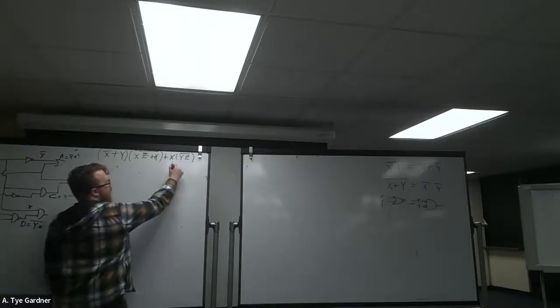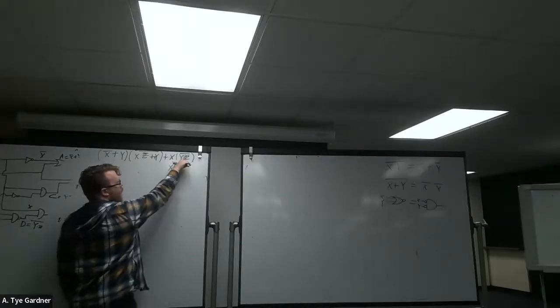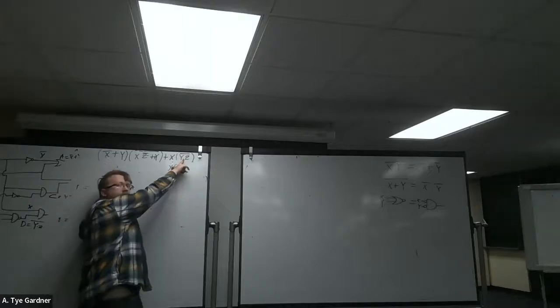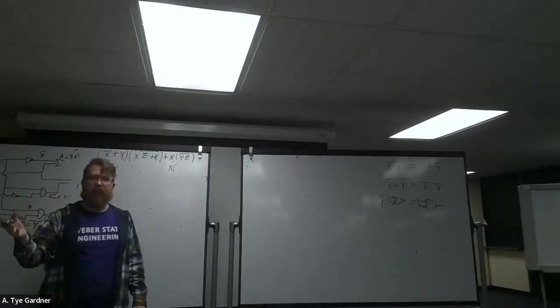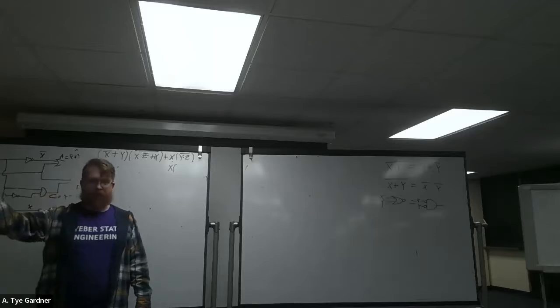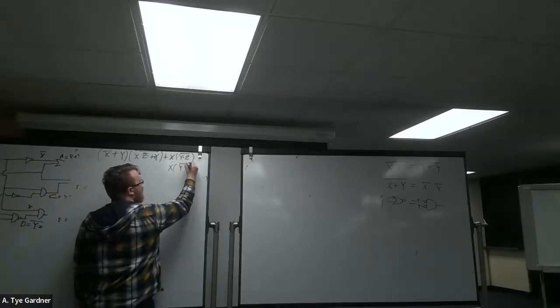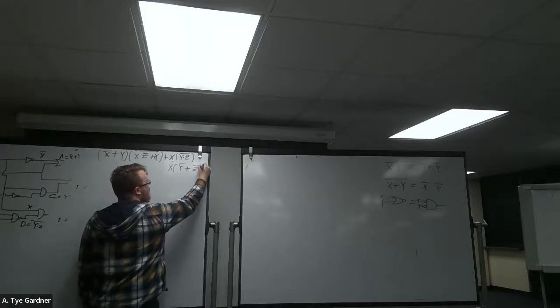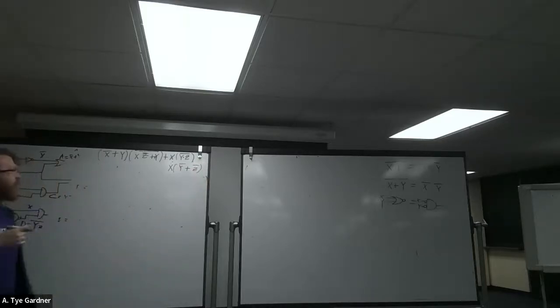So this term comes down, the X stays, and it's ANDed with, well, I flip the gate, which is currently an and. If it helps, explicitly write it. So ands become ors become ands. Or, and I have not Y or not Z, right? That's just straight up easy peasy De Morgan's theorem.